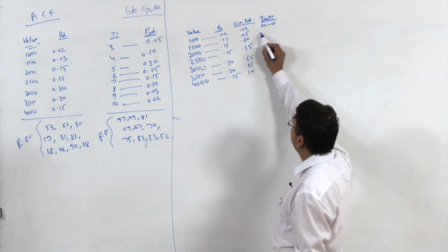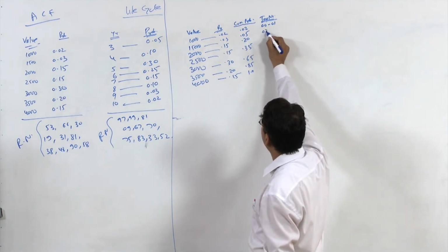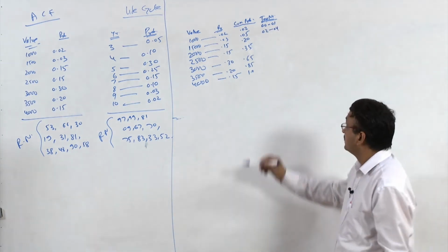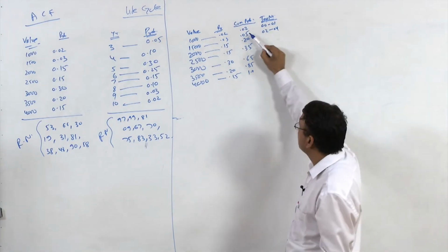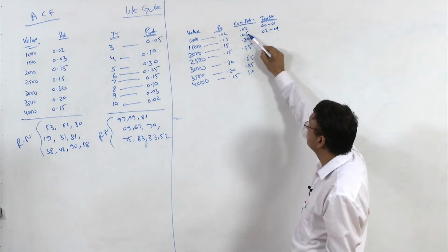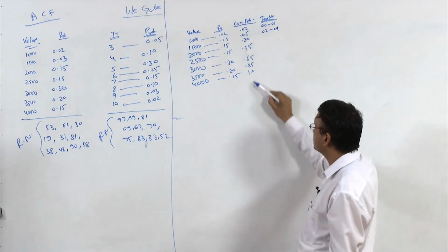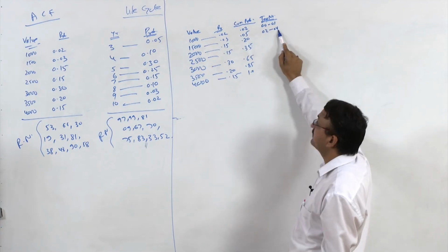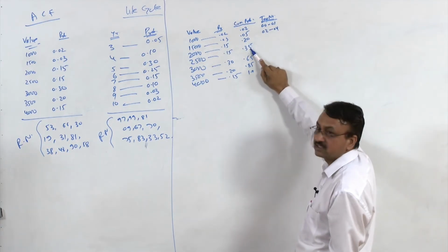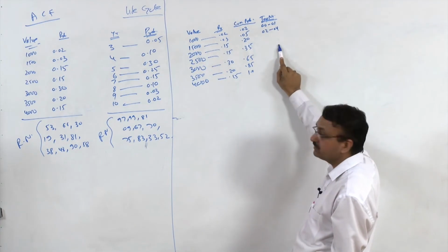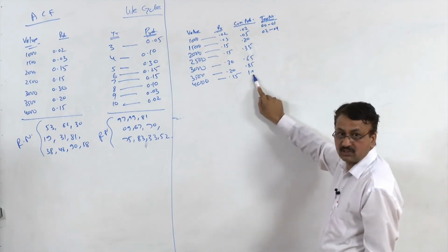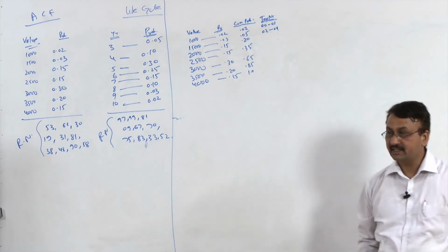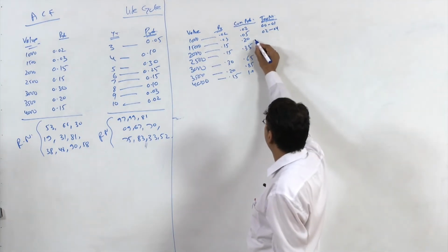So what would be the tag number for this? This is 02 and 04, right? Keep in mind, since this is 5, right? If you multiply all this by 100, then this would become 5. So this number should be 4. This should become 35. So the end number should be 34. This would be 100. So the ending number would be 99, right? So this is how you should assign tag numbers.